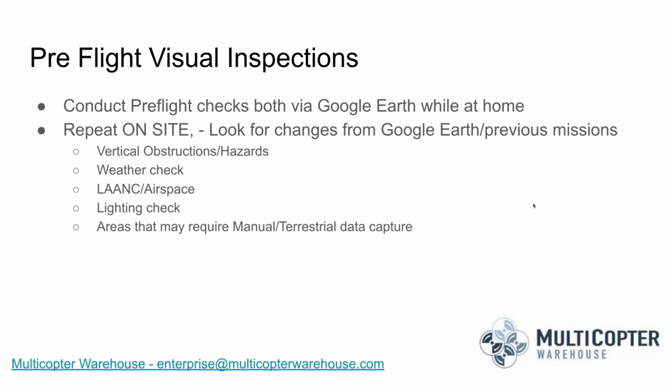You may find that if you're trying to make a 3D model of something, the complex structure of it might require some capturing of manual or terrestrial data ahead of time. So think of the areas you're trying to have represented in your final output and make sure you're capturing good quality images from the perspectives that you ultimately want to view or inspect your model or map from. And really, if you take all those things into account, you should have a very successful and productive mapping mission.